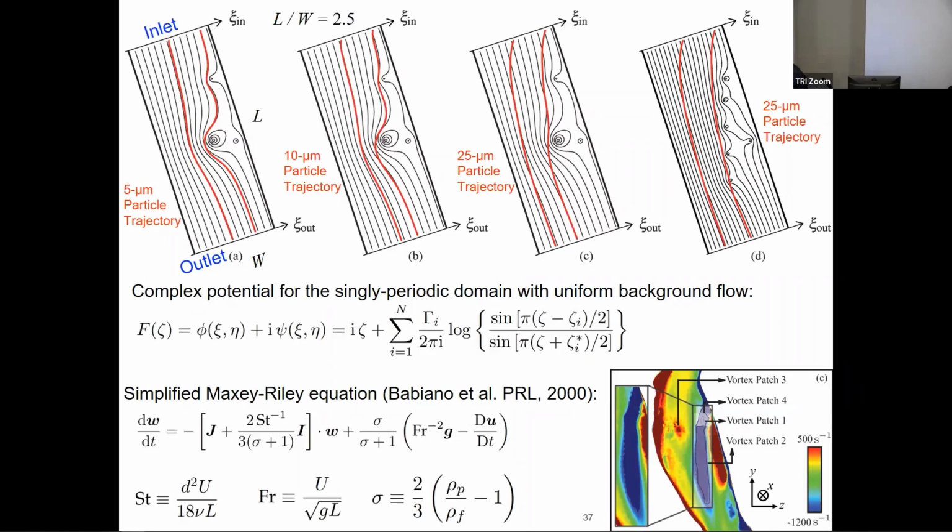So think about this section as a cross section that cuts through the region with the strongest vortex patches. Those are models that stand in for this region. The first 3 visuals are the same, as in this main vortex patch 2 is being replicated by one single point vortex with all the vorticity concentrated in there. All the vortex strength concentrated in there.